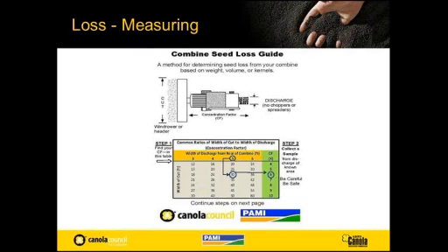And then you go down the chart into the gray area and you look for the windrow size that is approximately the same as what your cutting width is. So in this case, let's assume we're dropping it in a 5-foot band behind the combine and you're cutting with a 30-foot windrower. You've got a concentration factor of about 6. So for every 6 feet of cut width, it's going to land in 1 foot behind the combine. And most combines will probably run in that 5 or 6 concentration factor there. So it doesn't change a lot.